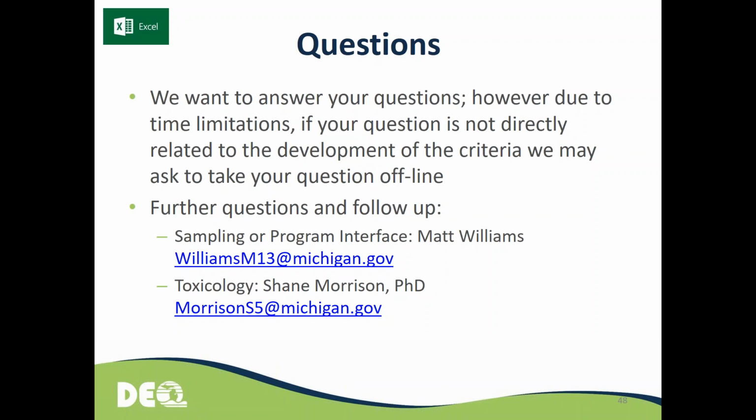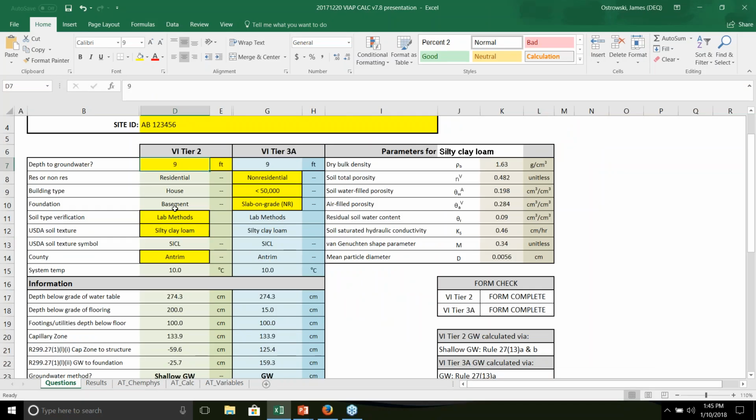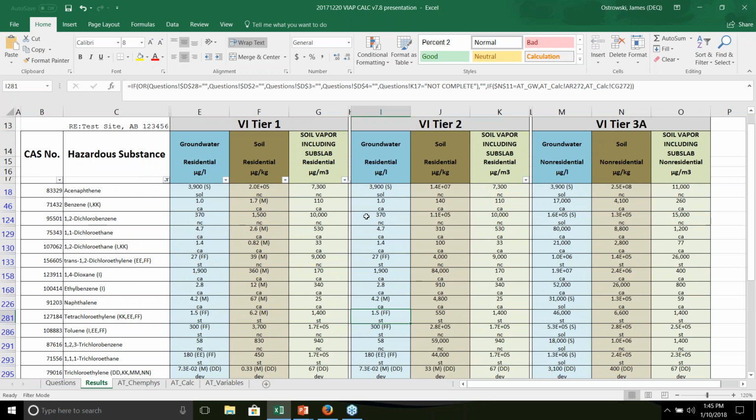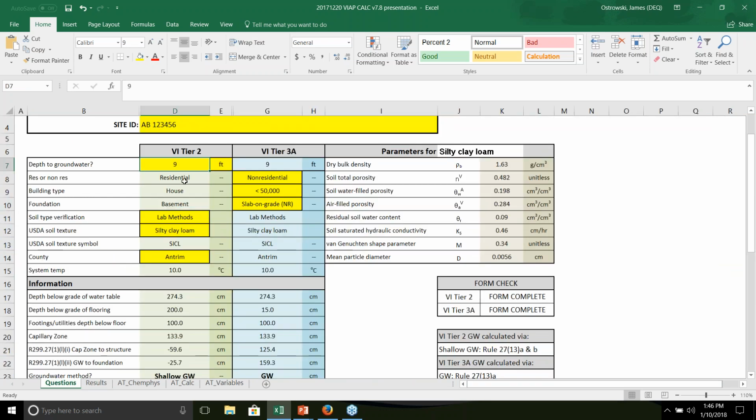The first question I have in front of me is, what happens when no groundwater is present? How do we handle sites that have groundwater that is not affected and soil contamination only? I think that's actually two questions. One is, what happens when no groundwater is present? When you have no groundwater present, and we can go back to the calculator, the groundwater values on the results table, you have nothing to compare to. The proposed rules say for the appropriate criteria, if you don't have groundwater for the appropriate media, there would be nothing to compare to. Because it doesn't change any of the other values, one of the things you could do is just put down to the depth you know. So if we only know to 10 feet, we can use that as what our investigation included to, and it would adjust that groundwater to that depth. That would be one of the things you can do.